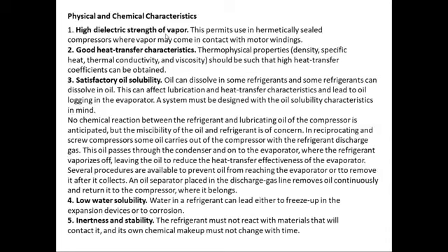Good heat transfer characteristics. Thermophysical properties, density, specific heat, thermal conductivity, and viscosity should be such that high heat transfer coefficients can be obtained, because your refrigerant goes to the condenser and the evaporator, which are the two heat exchangers. It should have a higher thermal conductivity, so that it can either absorb more heat in the case of the evaporator, or in the case of the condenser expel more heat into the environment. So high thermal conductivity is a requirement. For the same reason, higher viscosity and specific heat are required.